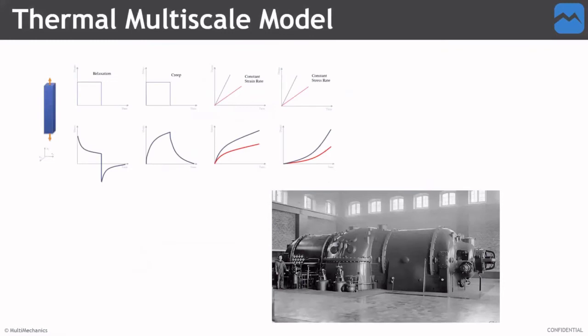The reason why this is important is because a lot of times with these composite materials, you do have properties that are dependent on the temperature. For example, in a lot of composites, you have viscoelastic materials that are rate dependent, but also dependent on the temperature of the material as well. And this can be done for, say, thermal cycling or just looking at the properties at different temperatures. However, it's also an issue with the processing of these materials. When you cure them, you're going to have some residual stresses within the laminate level as well as the microstructure level. And this second concept that I just discussed, we're going to go over and take a closer look through a model of a laminated composite.